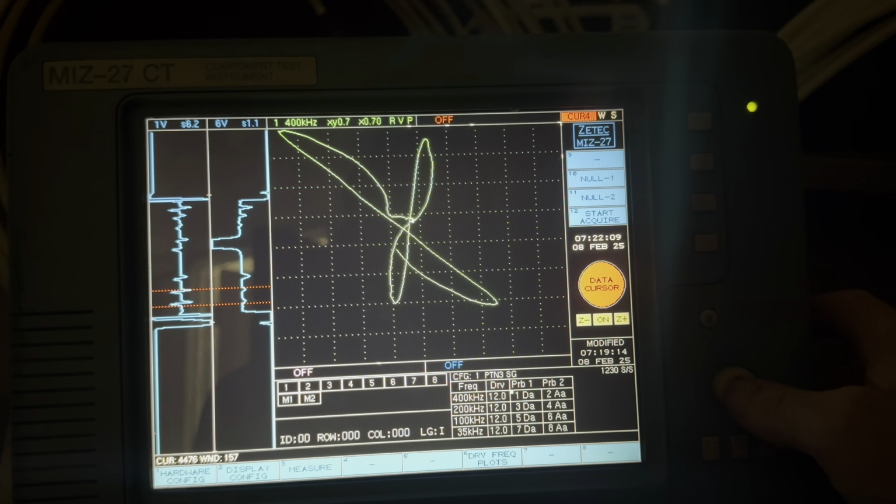And the display signal that you see here, what those represent are the timing of the eddy currents in the material that are disturbed. Eddy currents are swirling at every depth, provided you're using the right frequency ranges. And the signal that gets returned is the weighted average of all of the eddy currents from every depth. Some are disturbed, some aren't. But somehow between the coil and the wire that leads up to your instrument and all of your signal processing circuits and your output, the end result is the signal that you see.